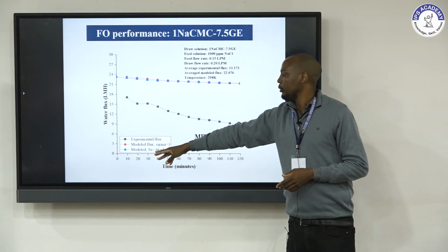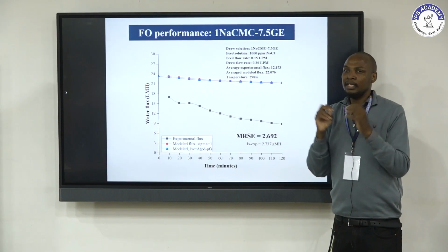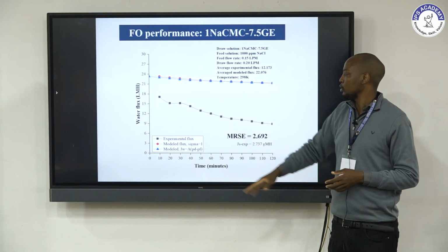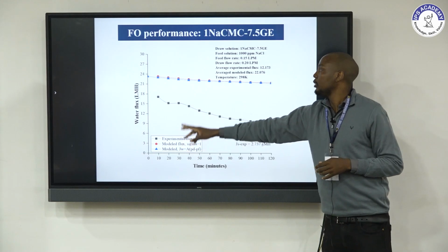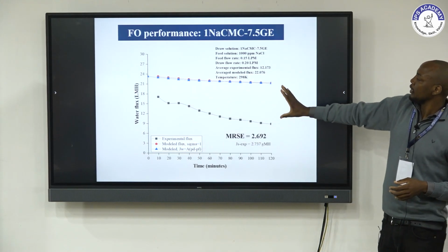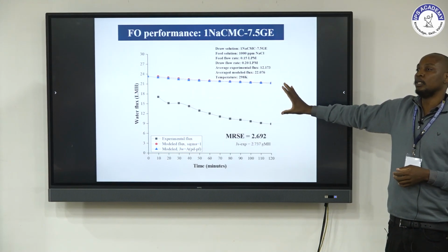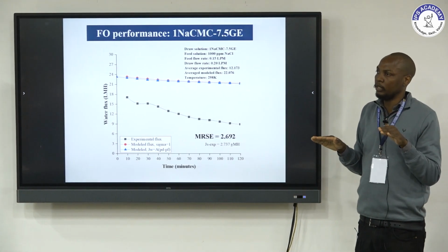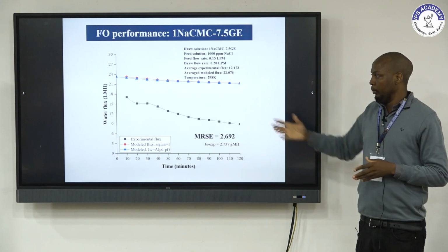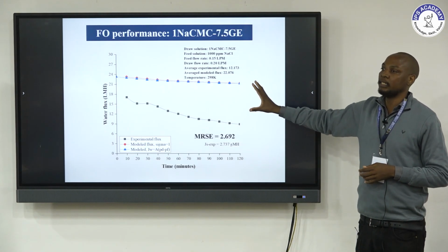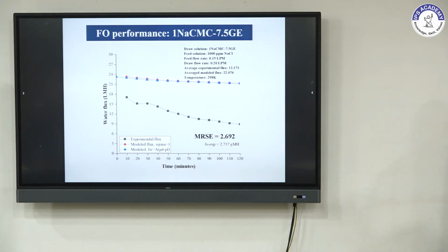Then this one, the third equation, because there's something called concentration polarization. So this model included it, but the blue one didn't. So you can see there's a gap here. And according to literature, the solution diffusion model doesn't include biofouling, so they're attributing that change to those factors.